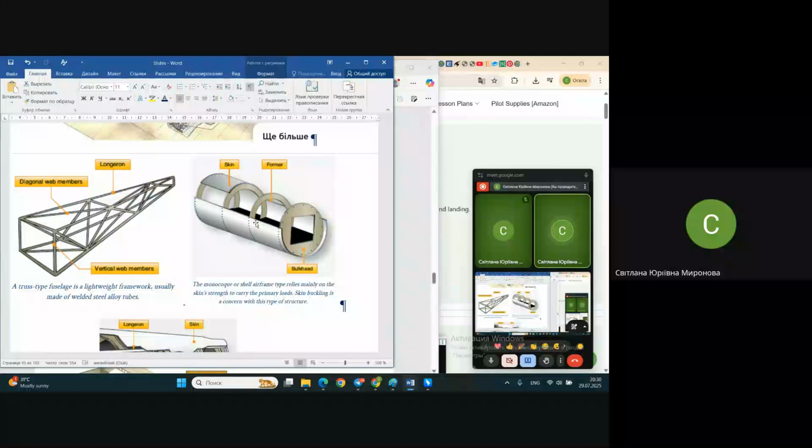Usually it's some portion of the fuselage where loads are not complex, not big, and where the shape of the fuselage itself may be rather complex. And it's just really an empty shell, rather thick, made of some stiff material, or made of composite material in modern conditions, for instance.